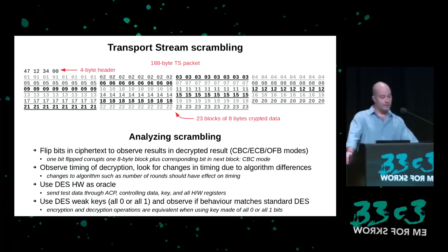At this point, I started to think I might be looking at doing a gate-level reverse engineering of the chip to understand this functionality. The chip's using technology that's older, so reverse engineering should be feasible. But if possible, I'd like to avoid all this extra work. It would be quite time-consuming and might give imperfect results similar to the optical ROM extraction. So I start with trying to characterize the scrambling modes.